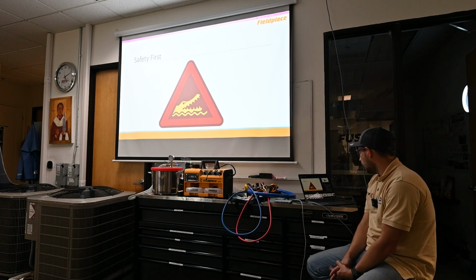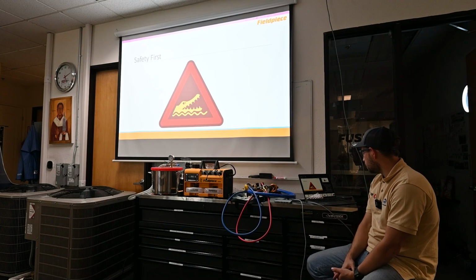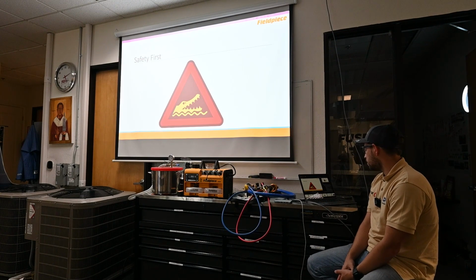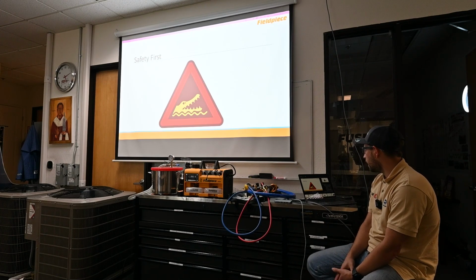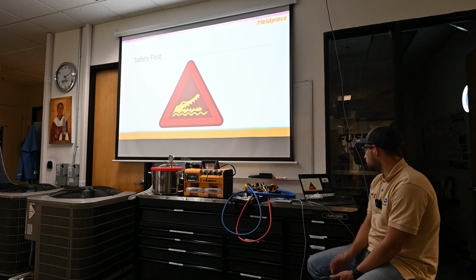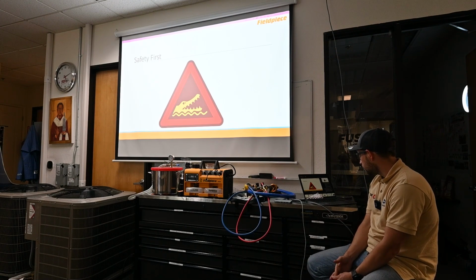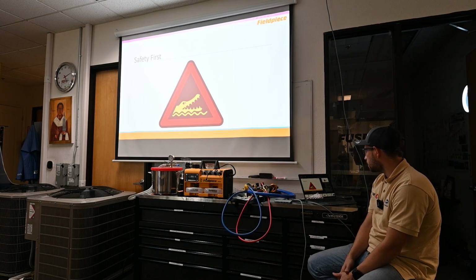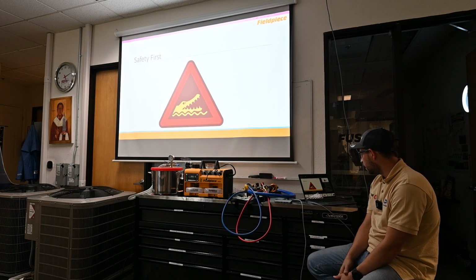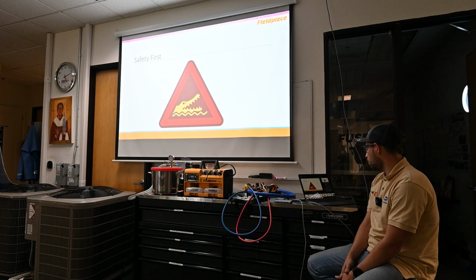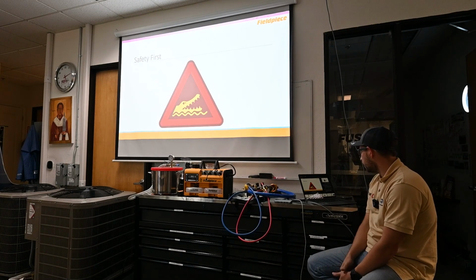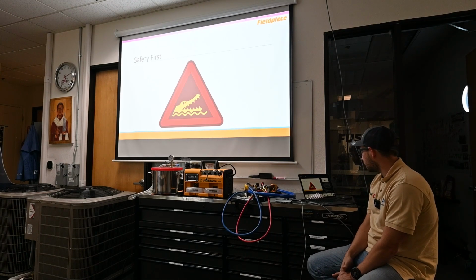Pressure in the systems. If leak test pressure from the systems is applied to the vacuum pump and hoses, a few things could potentially happen. Sudden oil discharge from the exhaust port is a very likely occurrence. Internal damage to the pump is possible. Some vacuum pump hoses are not pressure rated. If pressure is applied, this could fault suddenly. Pump exhaust gases can contain refrigerant, pure nitrogen, oil.